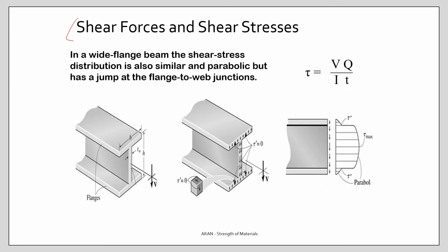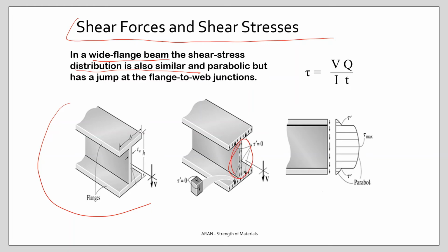If you look at other sections, like a wide flange beam, the stress distribution is also similar, but the web is actually where the shear stresses are acting.